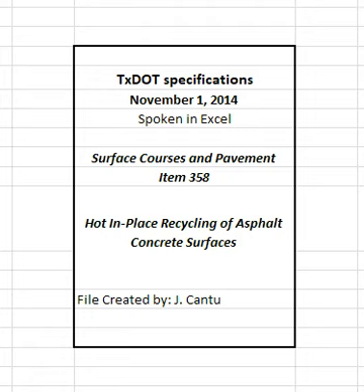3.1.2 Pavement milling heads. Provide milling heads for pavement recycling capable of uniformly loosening the entire pavement lane width to the depth specified on the plans. Accomplish the recycling by using milling heads that have a grade control system for each head. Ensure that the tooth spacing of the milling heads is enough to allow material to pass without excessive retention.